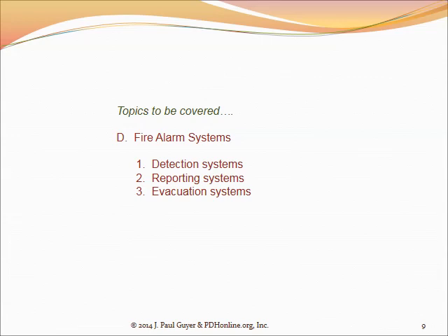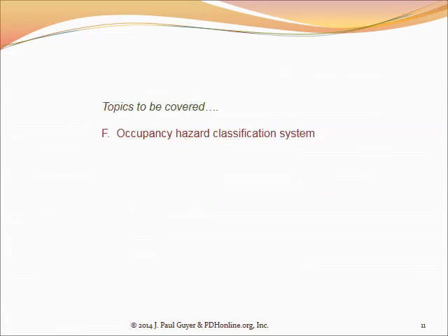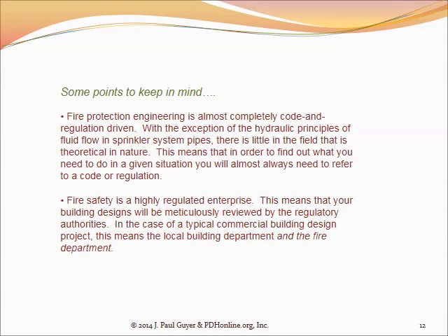These are some of the more common special occupancies and hazards that I'll have a couple of comments on here and there. Okay, this is a point that I like to make whenever I'm giving this webinar. Fire protection engineering is almost completely code and regulation driven. There's almost nothing theoretical that you're going to encounter in fire protection engineering. The only thing that's theoretical, if you will, is the hydraulic design of the pipes for an automatic sprinkler system. There you're using the stuff that you learned about the flow of fluids in pipes.